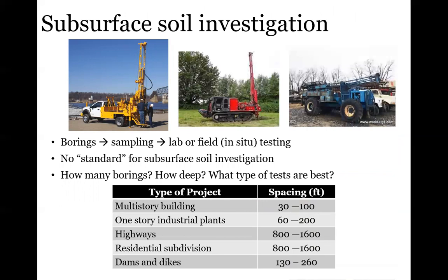Because if you think about it, you're drilling a hole that's 2 inches in diameter, and then you are hoping that that is representative of the entire 100-acre site, or a couple acres. If you actually look at it, the percentage of the area that we're investigating is usually less than 0.1% surface area wise. So there's already a lot of inherent error built into that because we have a lot of uncertainty of not being able to test the entire location.